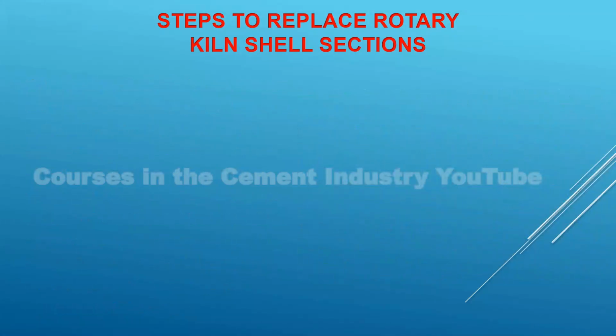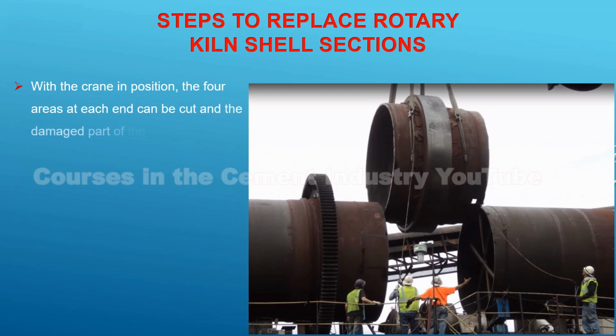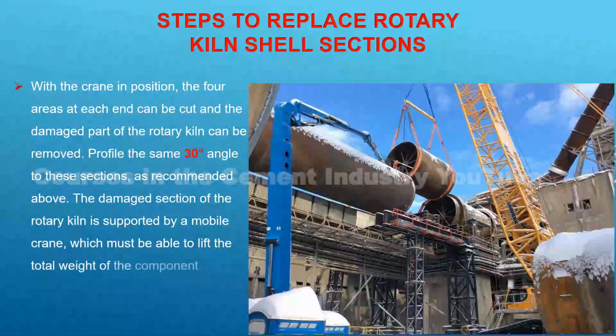Step 12. With the crane in position, the 4 areas at each end can be cut, and the damaged part of the rotary kiln can be removed. Profile the same 38° angle to these sections, as recommended above. The damaged section of the rotary kiln is supported by a mobile crane, which must be able to lift the total weight of the component. See this video.